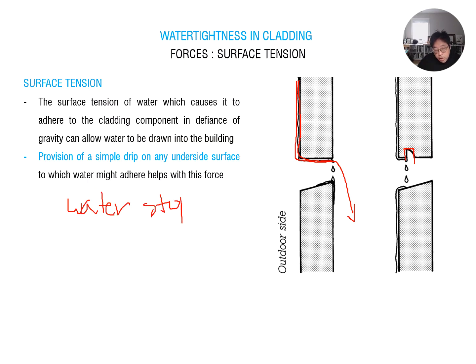Even when you design a concrete slab, and you have your glass and window frames here, and this is exposed concrete, you always have to provide this water stop.